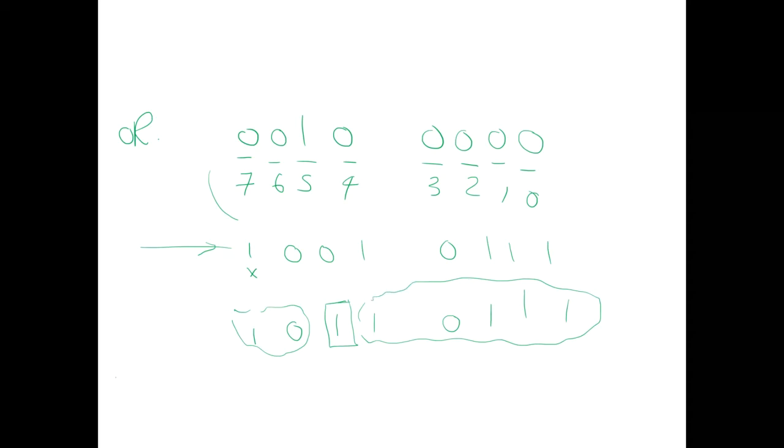Now the next line was to NOT it with 0x20. Then closing in C permits us to call. Yeah, that's the point. That's what I'm trying to show you, that it's faster because we're not using any functions, but also we're able to change multiple pins at the same time. Yes, exactly. Well done.